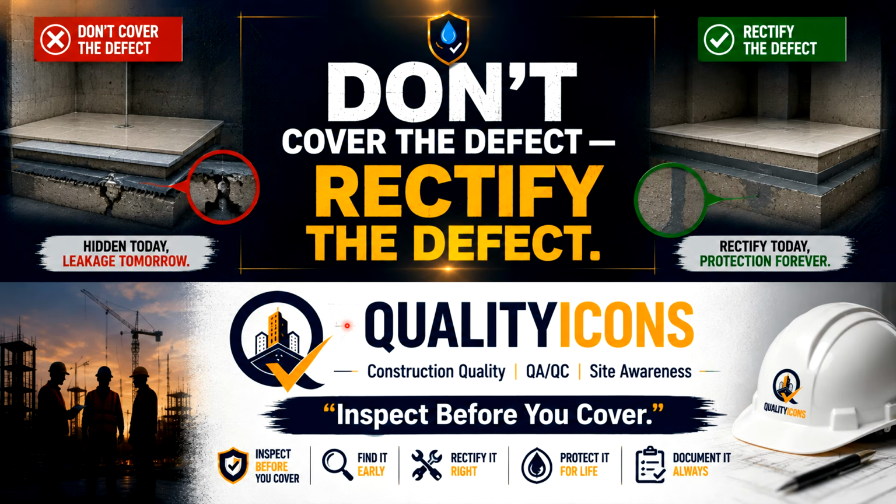Let's look at the practical impact of quality control. Imagine two identical toilets. In toilet A, the team skips pre-ponding, directly applies the waterproofing coating, completes screed and tiles, and hands over the apartment. Three months later, leakage.